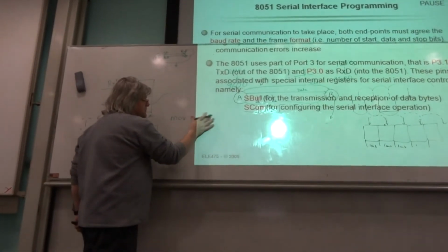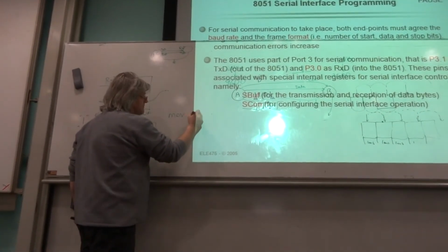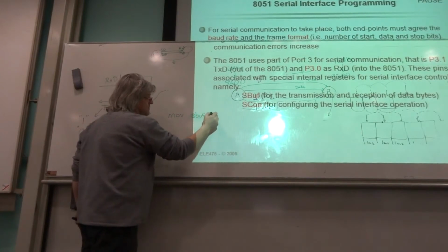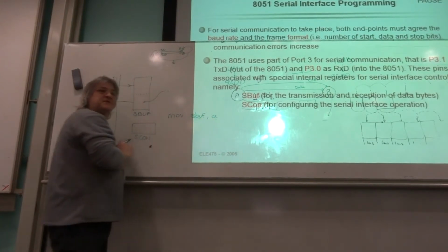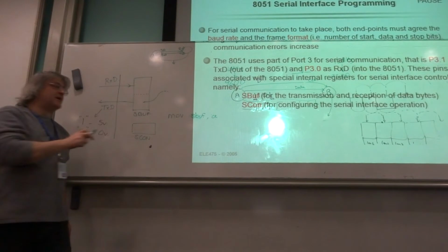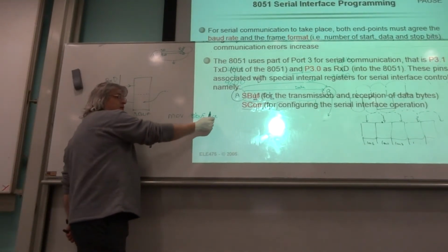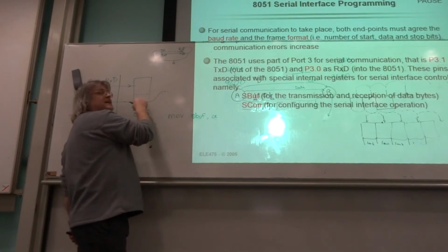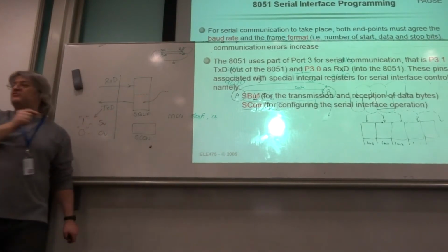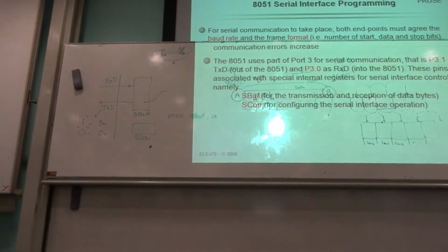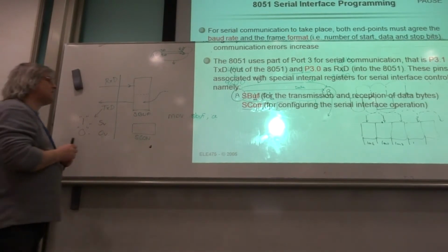You say, move the contents of the accumulator into SBUF. Remember, source and destination. The process of doing that, we'll put it in here. As soon as anything's written to SBUF, it will automatically be transmitted. Okay?